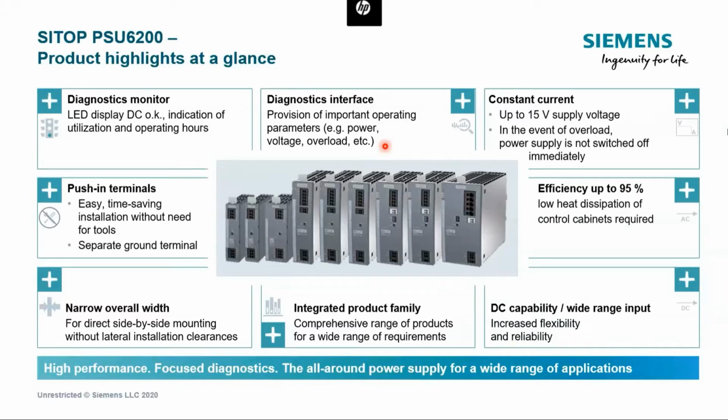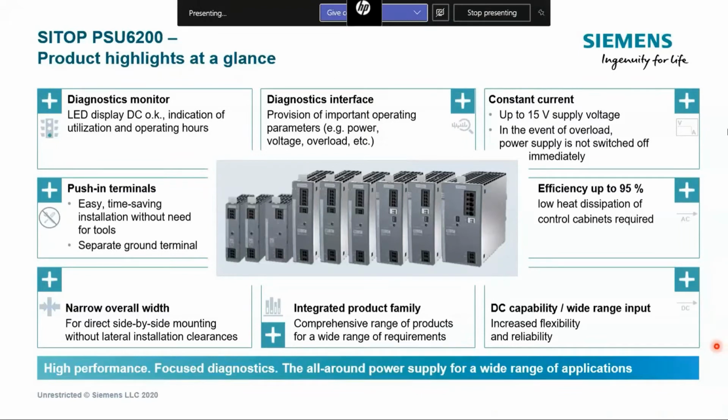We actually transmit information over this digital input, and we have pre-made function blocks to be used with the PLCs in order to read information from the power supply itself. This information includes how much current I'm supplying, what the voltage is, the temperature, and several other pieces of information that we can read over this diagnostic interface.